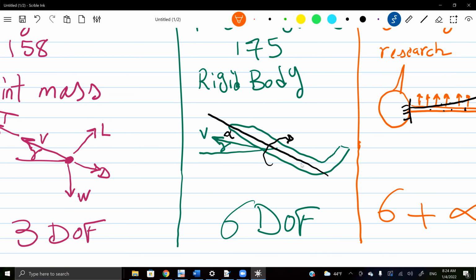So this is actually an issue, and this is the main difference between the performance and rigid body: whenever you command the climb, I want the velocity vector to go from horizontal to upward, like in this picture. Well, this may not happen. What may actually happen is that the body rotates, and indeed, this is what happens.